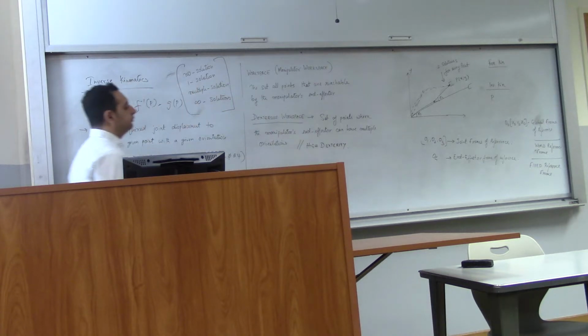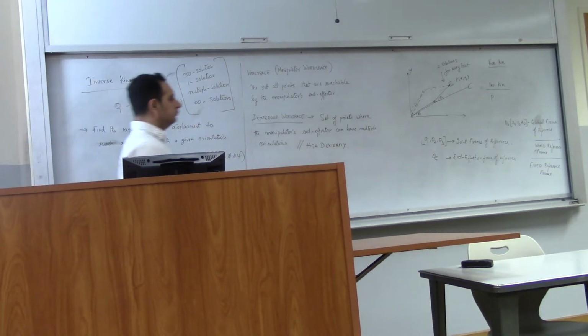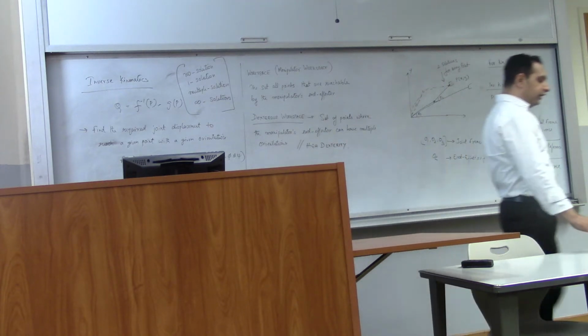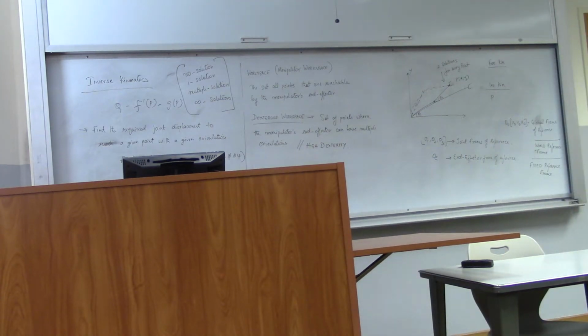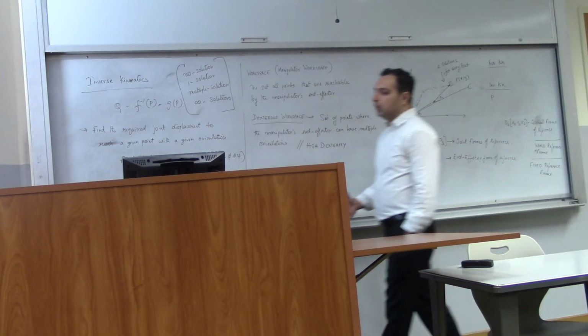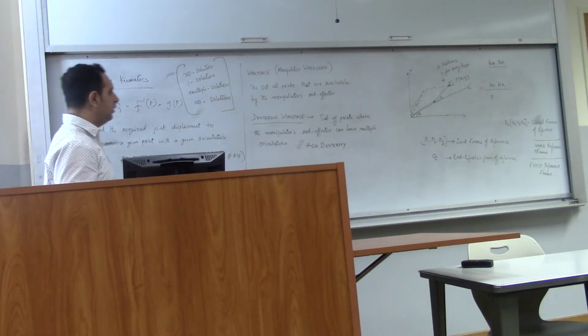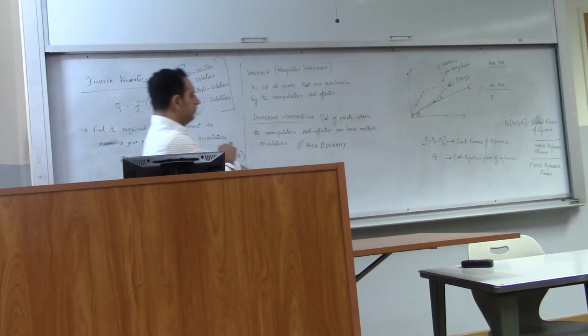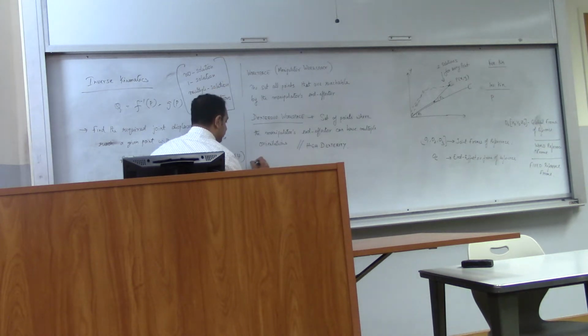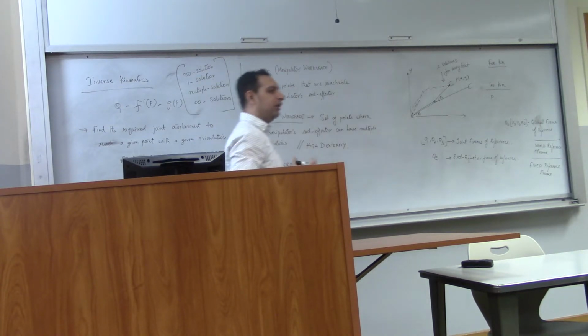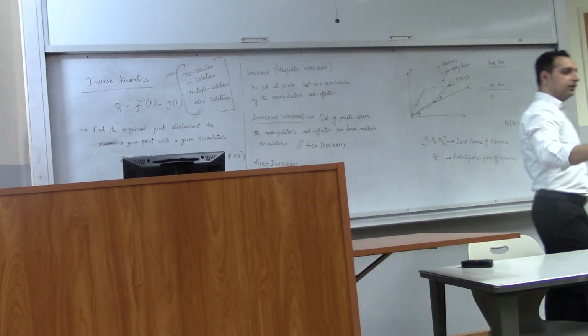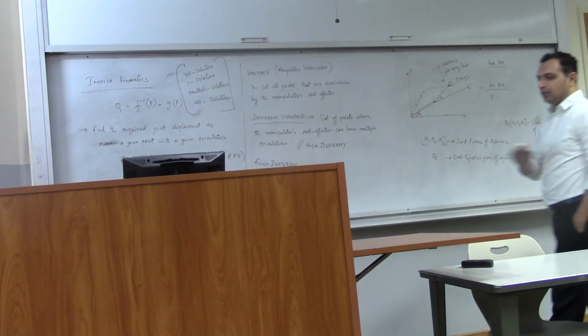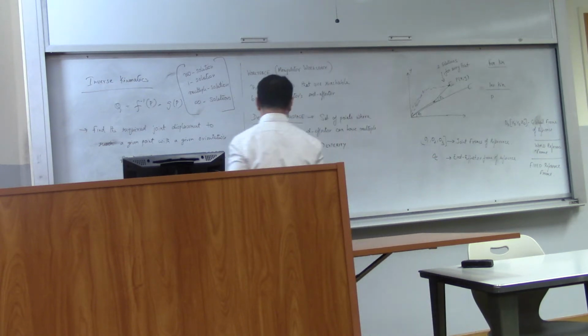Okay. There is also what is known as a fully dexterous workspace. Fully dexterous workspace means you can generate any orientation you want. It's not limited to a few orientations, but basically any orientation you want can be generated by the manipulator. So the first definition is high dexterity, that means you have multiple orientations. But full dexterity is you can have any orientation you desire in 3D space.